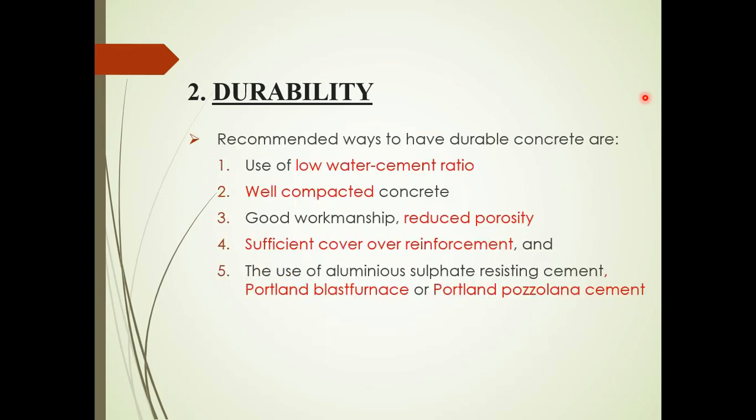Okay, how do we improve the durability of the concrete? The recommended ways to have durable concrete are to use a low water-cement ratio and to compact the concrete well. We provide good workmanship so that we can reduce the porosity, use sufficient cover over reinforcement for reinforced concrete, and also use sulfate-resistant cement, Portland blast furnace, or Portland pozzolana cement to improve the durability of the concrete.